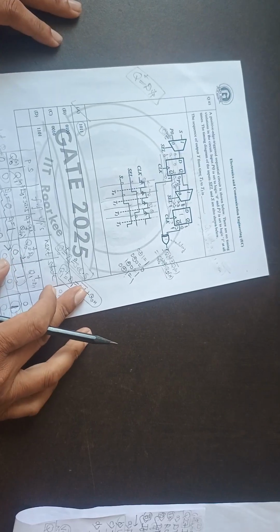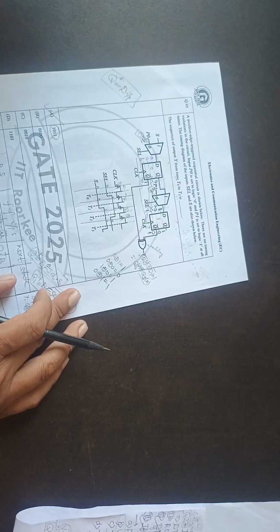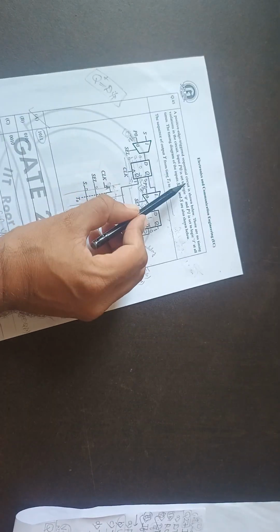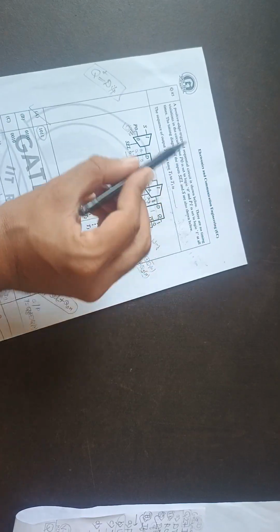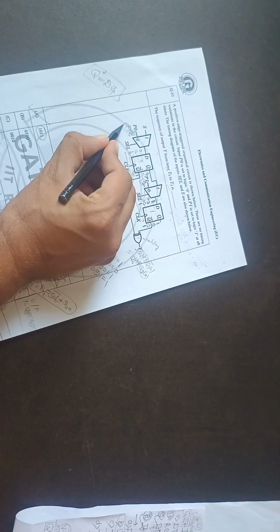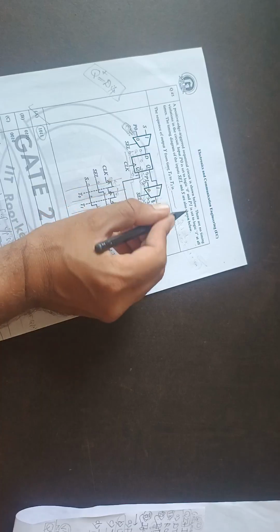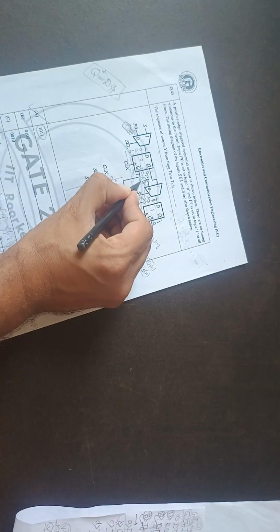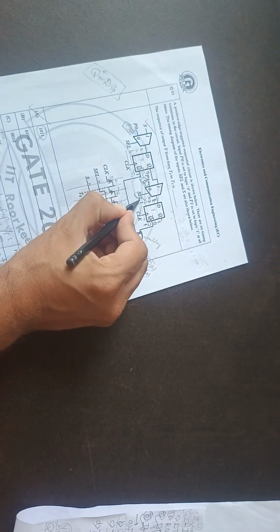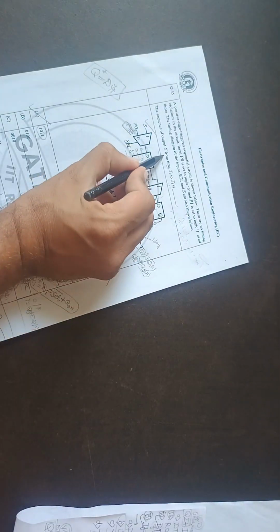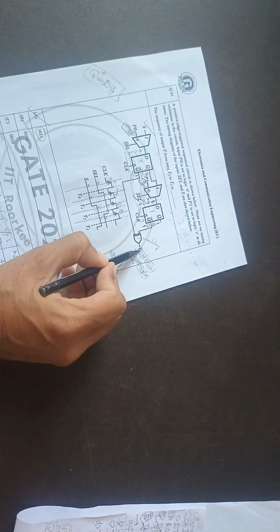Next question is on the sequential circuit part. It is a tricky question. It says that a positive edge triggered sequential circuit is shown below. There are no timing violations. Input P0 is set to logic 0, so this part is set to logic 0 at all times, and P1 is set to logic 1, so this part is set to logic 1 at all times. The timing diagram of select and s is given. We need to find the sequence of output y from time t0 to t3.